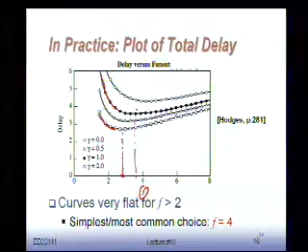So that's what really matters. If I take 4 or 3.6, the difference in delay is going to be very minor. And that's why we say, okay, stick to 4. Don't make it 3.6. It's a lot easier. Just size everything up with a factor of 4, and you're going to be perfectly in good shape from a performance perspective. And once I know that, then I can compute exactly how many stages I need, right?